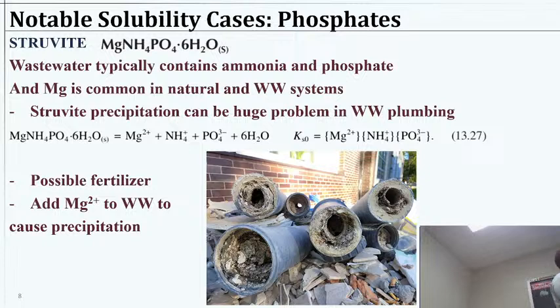You could have contamination coming in from the outside. And if you had any lead in the pipes that were put in there a long time ago, or in the soldering joints or anything like that, then you're leaching the lead right out into the water, right? So there are all sorts of reasons why we would promote mineralization in the drinking water systems, but just a little bit. Replacing them after 100 years makes a lot more sense than letting them corrode.